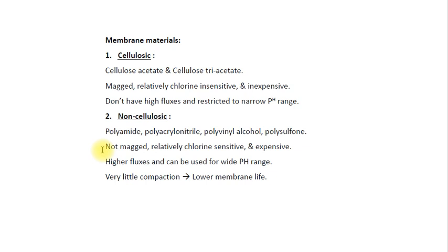Okay, so for that we are preheating the water in our home appliances. In our home appliances we also have a mechanical separator, a micro filtered separator, where we can remove the small solid particles. Then we have the carbon cartridge, which can be used to separate out the chlorine and other dissolved gases in the water. That pre-treated water is then sent to the polyamide reverse osmosis membrane, where it will be purified. So these two types of membranes are used in reverse osmosis.